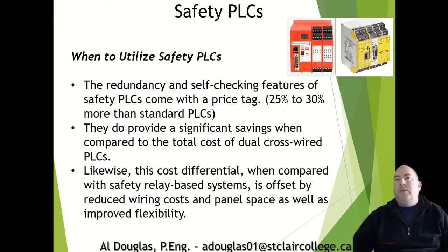A safety PLC is a more modern version of this because we can do a lot of different safety functions all within software. And all the redundancy and self-checking are all internal to that. More expensive to do it this way, but this is the way almost everything is done now.